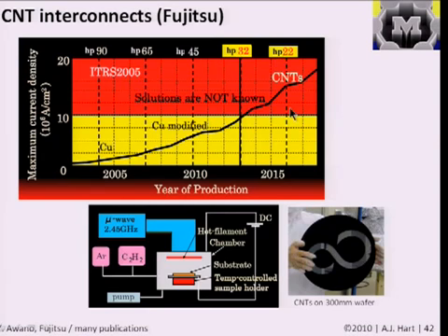So for that, they've been trying to develop processes that integrate nanotubes in a very large and parallel fashion on their substrates. So, for example, they'll use a chemical vapor deposition process using a plasma to grow carbon nanotubes over a full silicon wafer. And this is just an example of their logo grown over this wafer, but showing that they're able to get very uniform growth of nanotubes over these large area substrates.